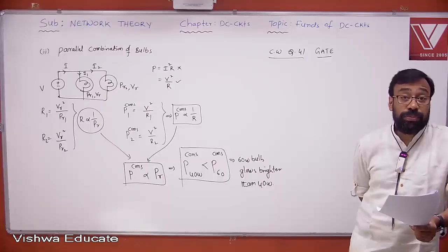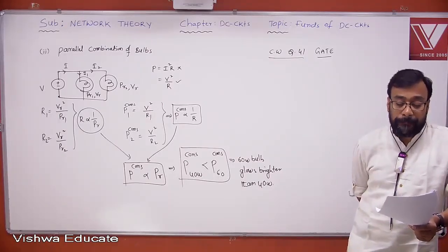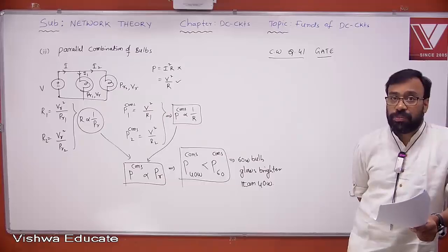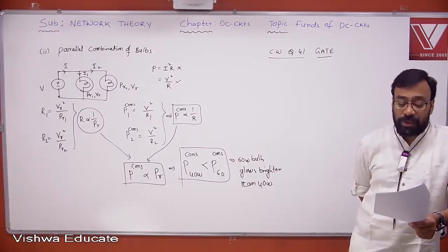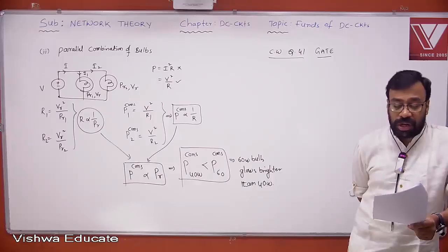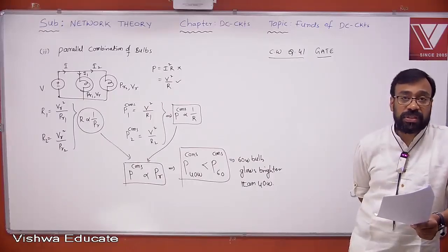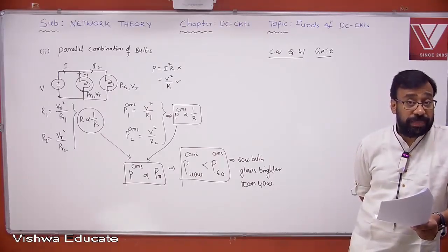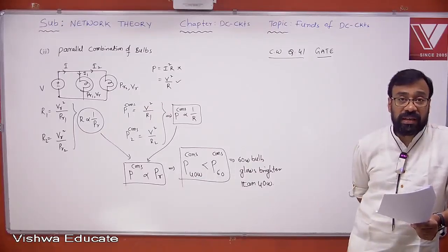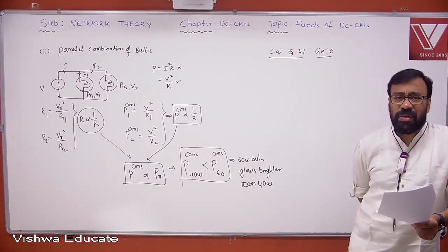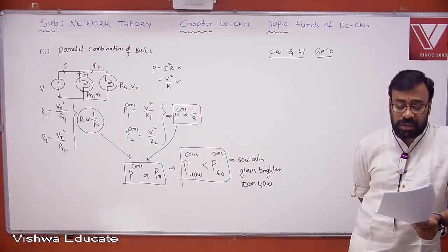Most of the times people may make a mistake, since the first option is very tempting. Okay. So be careful. That's not the correct option. The bulbs together consume 50 watt. I'm not sure about 100 watt and I'm also not sure about 50 watt, because I do not know how much voltage is appearing across each and every bulb and what the voltage rating is. It's not possible. You cannot say. Option C. 60 watt bulb glows brighter.